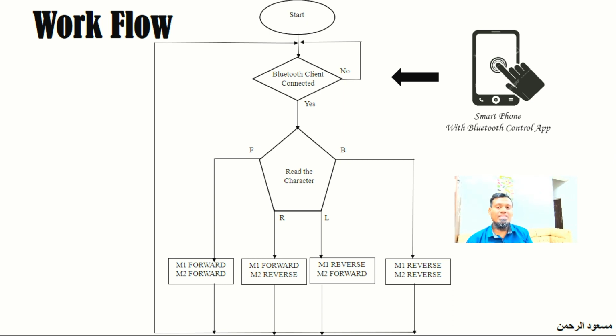So what is the difference between these two is, if you electrify the motors in opposite polarities, it will have a quick turn. To turn slowly, you can make the voltage of one motor 0 and give the voltage for only one motor. So this is how you can create changes in the turning time period. Likewise, same for the left side also. If you give a command, it will be received and the operation will go on accordingly, and it will continue until you send the next command.